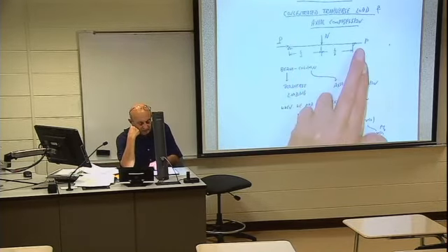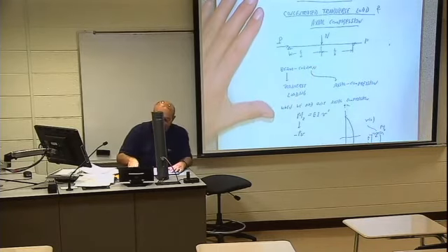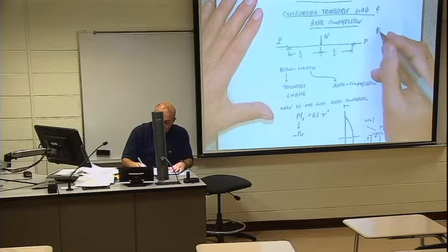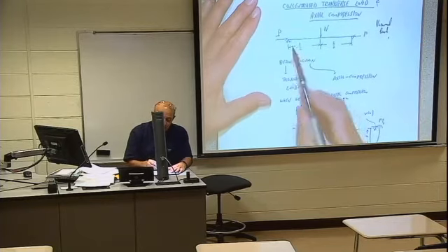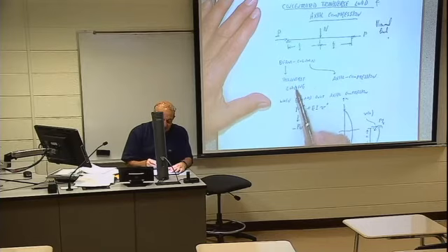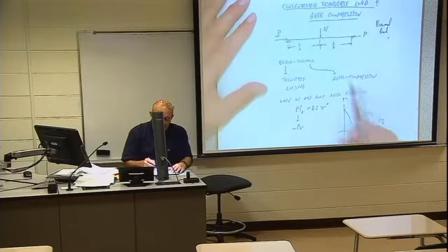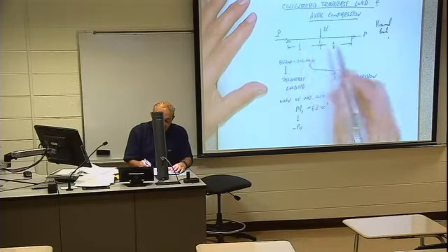P and P. Here is a load N. Why did I note N? N, normal load. So this is now, actually, called a beam column. Why beam? Because transverse loading is here. A beam usually works on transverse loading. Column, but there is axial compression.